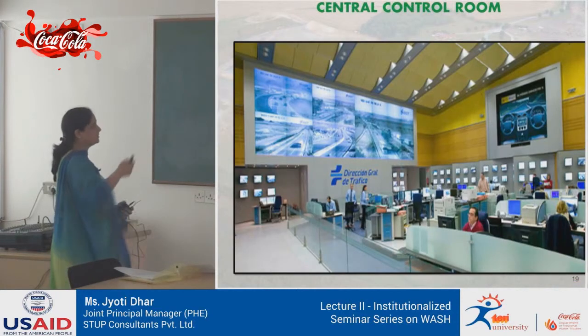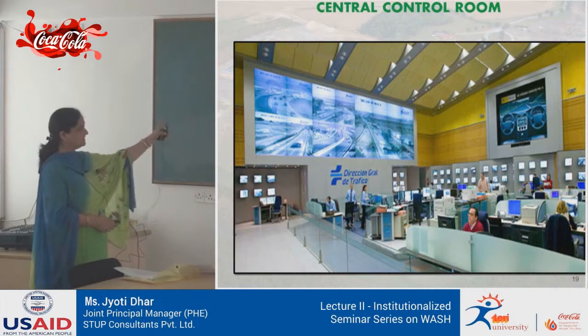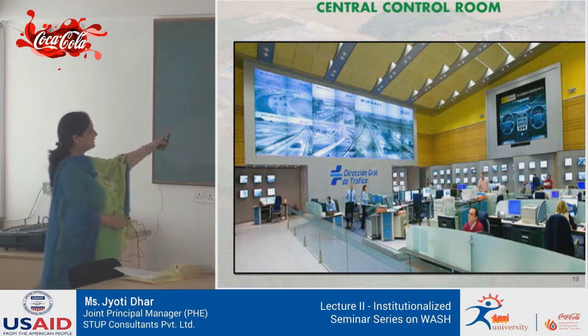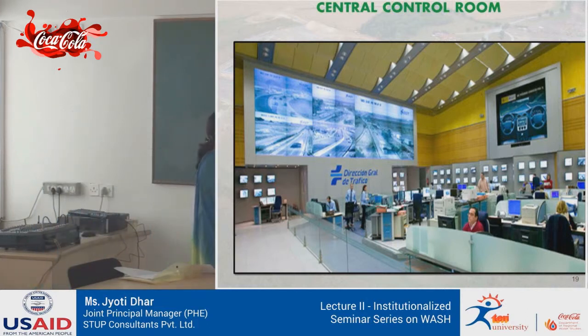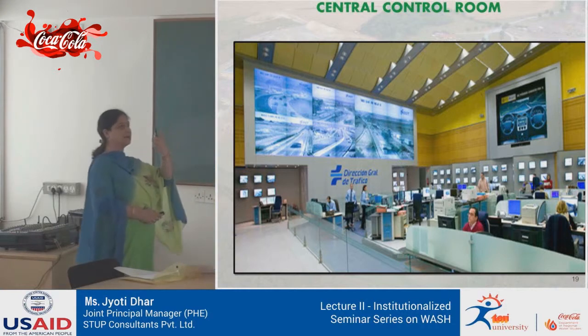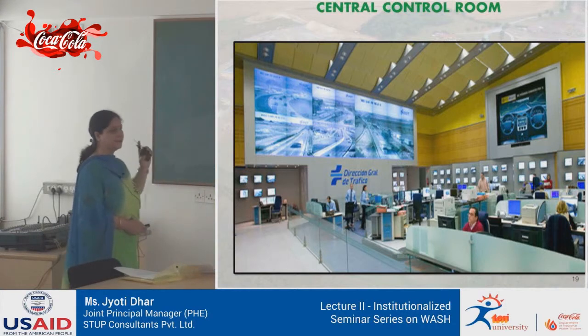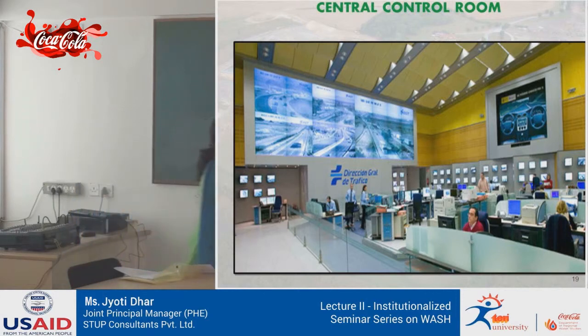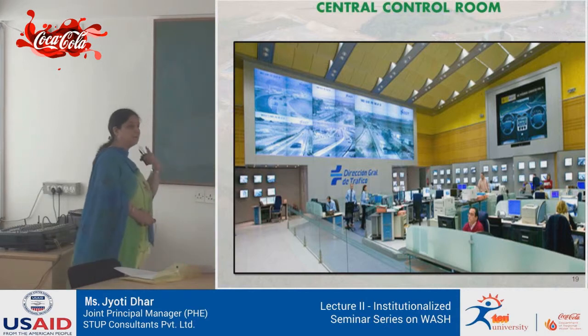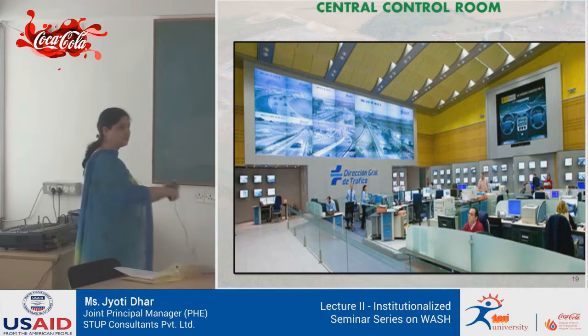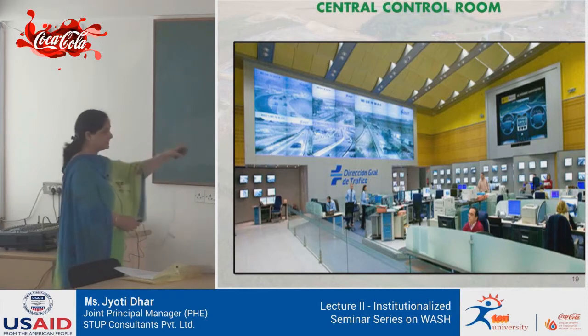And this is a central control room wherein you can see a big display and you can get screenshots of each and every area. Even nowadays your CCTVs, cameras and everything, can be integrated into your SCADA system. So you can view what is going on there. Maybe some operator is going and deliberately switching off the pumps or doing some mischief. You can see on the screen from the central control room.